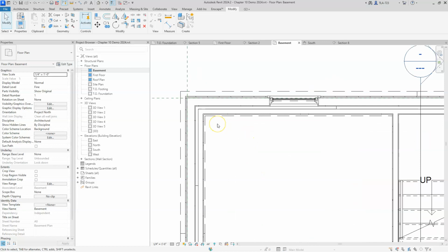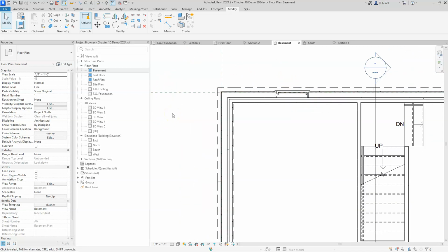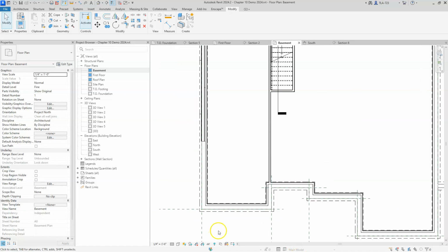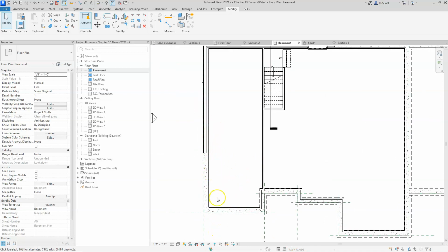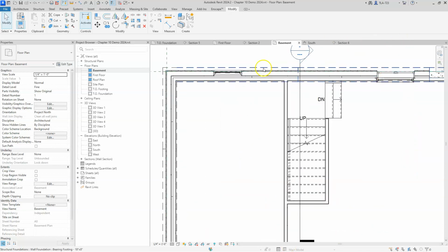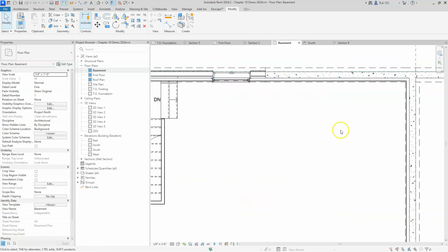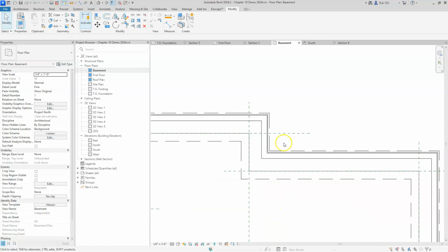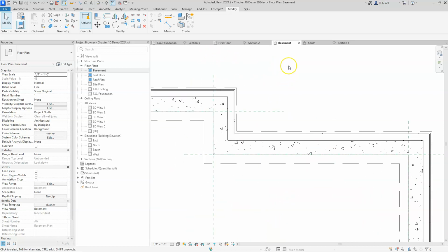We're going to define the boundary of this floor where. And that's a question that you should always ask yourself. Make sure that you know you're being deliberate and you know what it is that you're trying to accomplish. Now it is easier to see over here because, as I mentioned before, we have a stepped foundation. So we have a combination of foundation wall at the 4-foot level, and then over in this area we actually have a framed wall at the 4-foot level. That's where our cut plane passes through our wall, which is why these walls look different. But the boundary of the floor doesn't really care what kind of walls are up on top of it. The boundary of the floor should start where? And if you answered the inside face of concrete, you are correct.